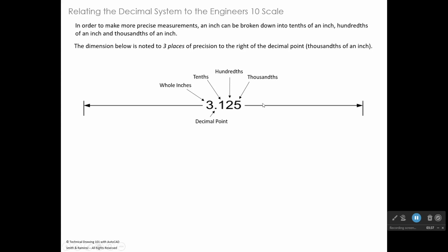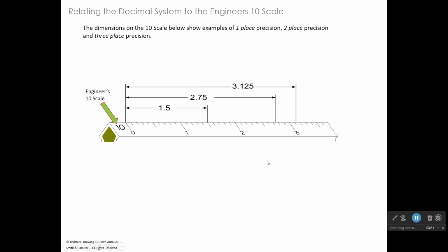So if you could take a piece of printer paper and shave it into 4 different pieces through its thickness and just take one of those, you would have 1,000th of an inch. So you can actually feel 4/1000ths of an inch pretty easy. You can feel the difference in that.